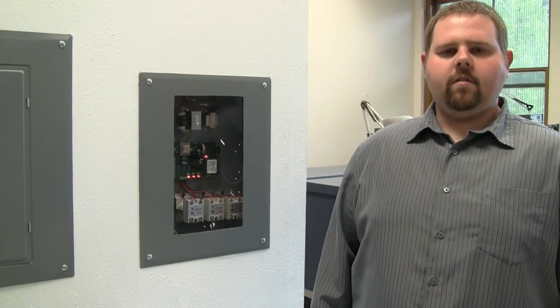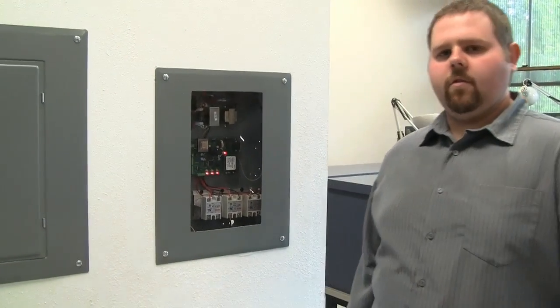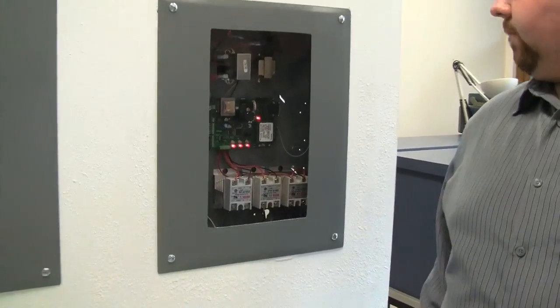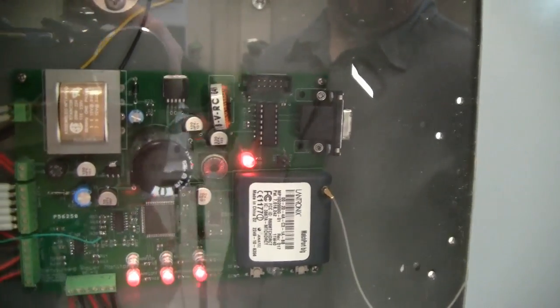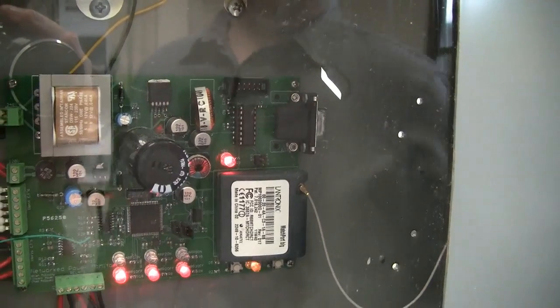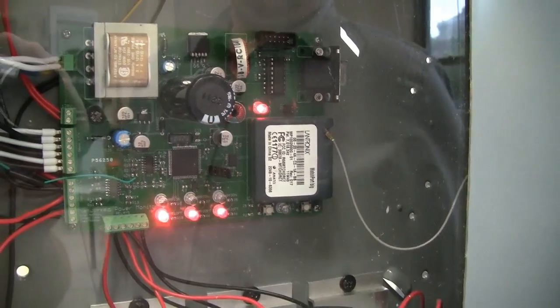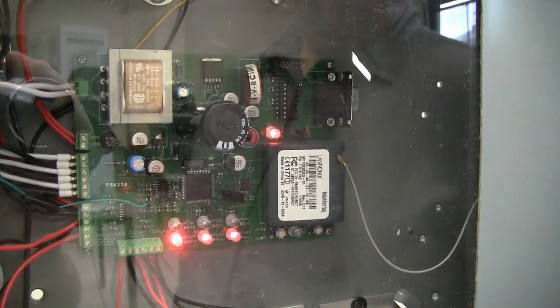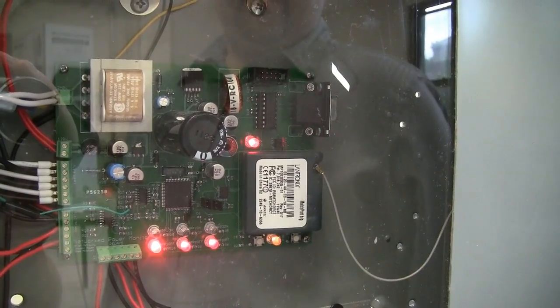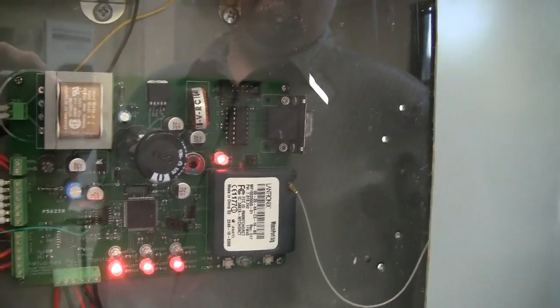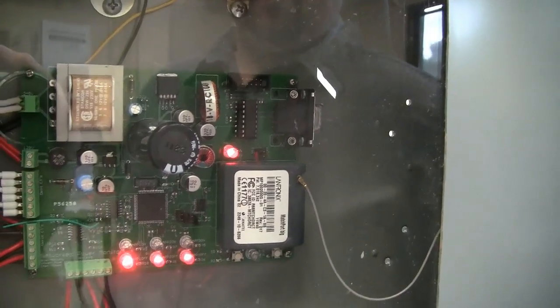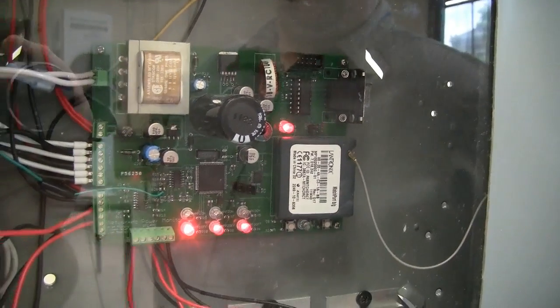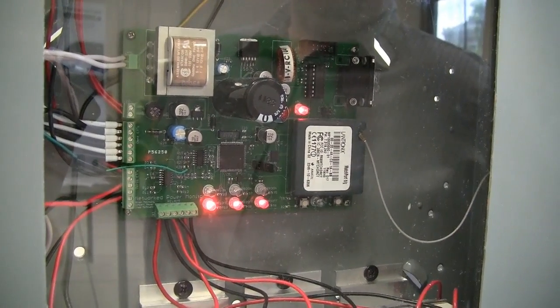Another unique design solution is the use of a MAX232 chip. This chip serves two purposes. Firstly, it serves as a troubleshooting device. As previously mentioned, data between the microcontroller and network controller is transferred via UART. With the use of the MAX232 chip, a DB9 connector, and a virtual COM port on the computer allows us to physically view the data being transferred between the microcontroller and network controller to make sure it's correct.